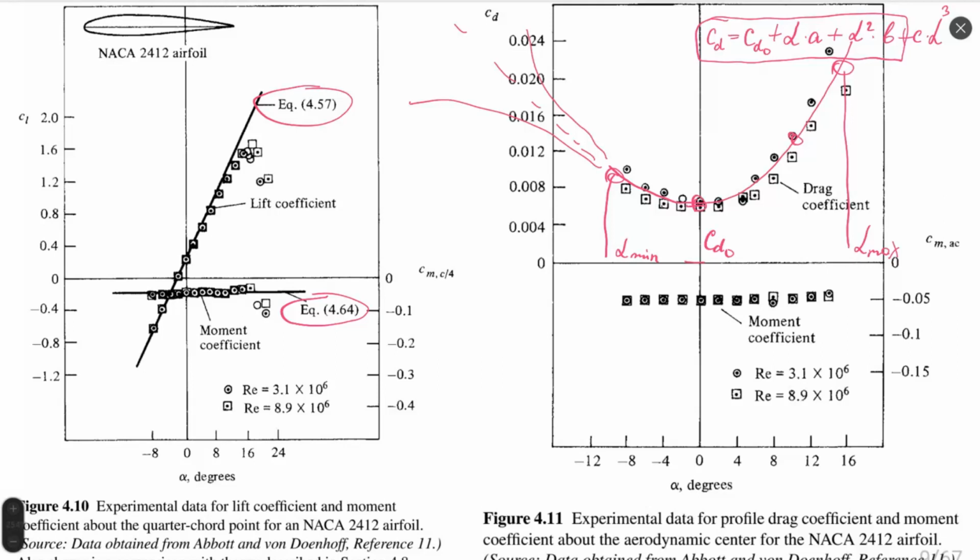Or let's say it's a divergence we might see, which will not allow us to extrapolate data. Extrapolation is a very bad idea in aerodynamics. It is probably the worst thing you can do, because the function can go in a completely different way than you expect. So I recommend that if you use such approximation methods, you work inside the region where you know data.